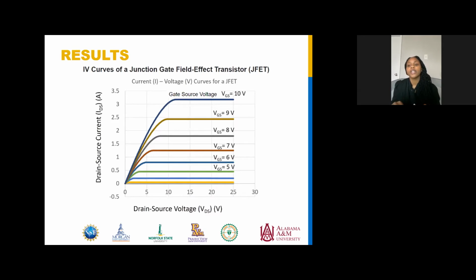The junction field effect transistor has a narrow piece of high resistivity semiconductor material forming a channel of either N-type or P-type silicon for the majority carriers to flow through, with two electrical connections commonly called the drain and the source respectively.